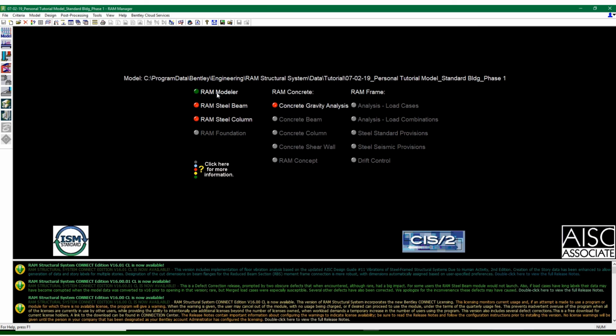There were some default boundary conditions set here, and that's what RAM has in terms of understanding the fixities of each point. Just so you know, gravities are pin, pin, and fixed for torsion, obviously, but they're pinned models. But I think they actually might be pinned for torsion just as well. But it doesn't matter for what we're doing.